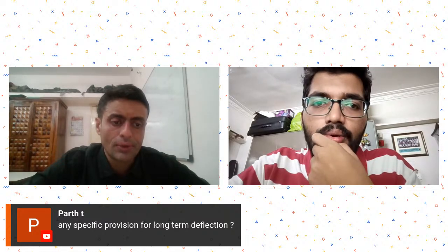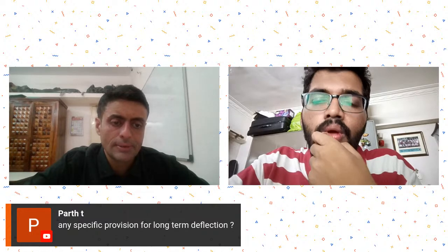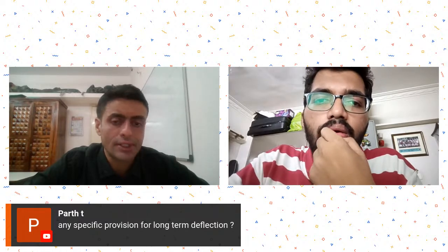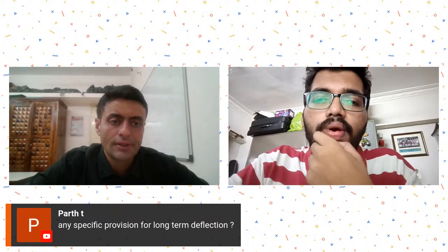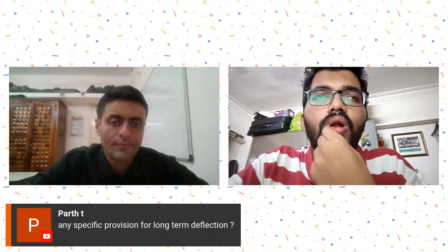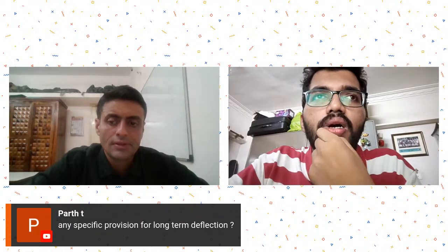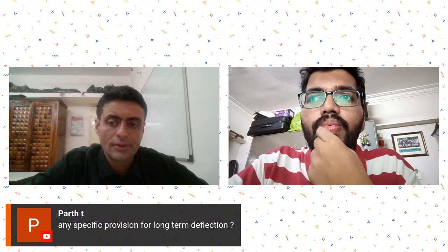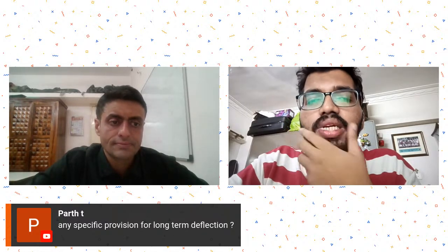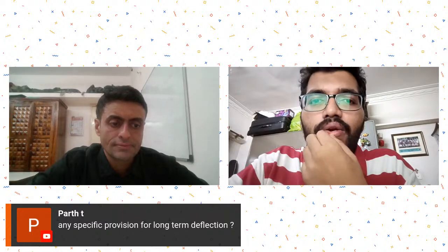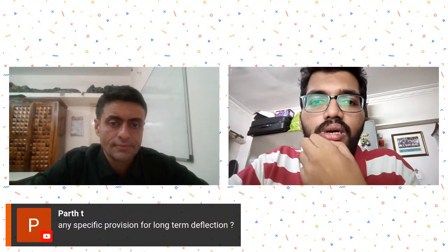Parth is joining from Pune. He's asking any specific provision for long-term deflection. So long-term deflection, that we would be basically checking as per L by 250 as per the code.